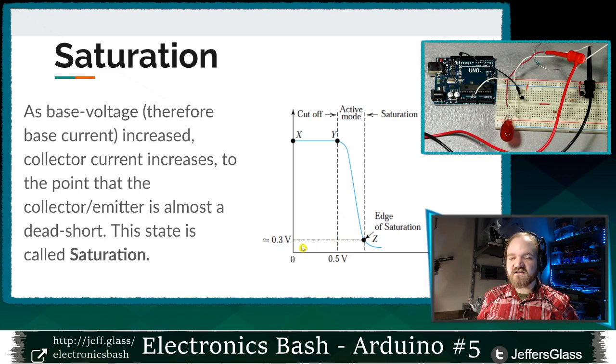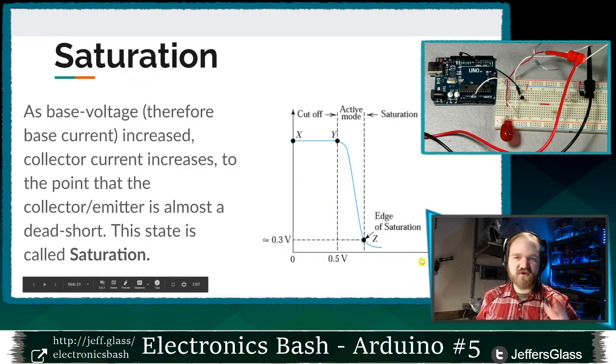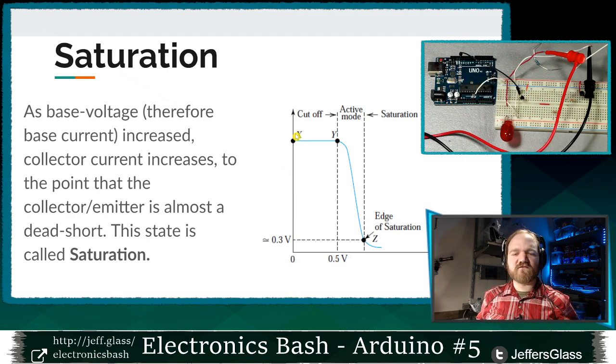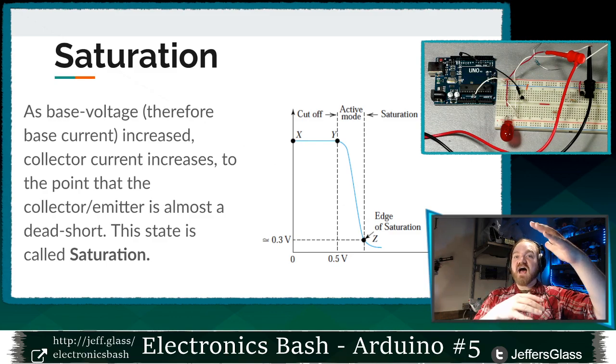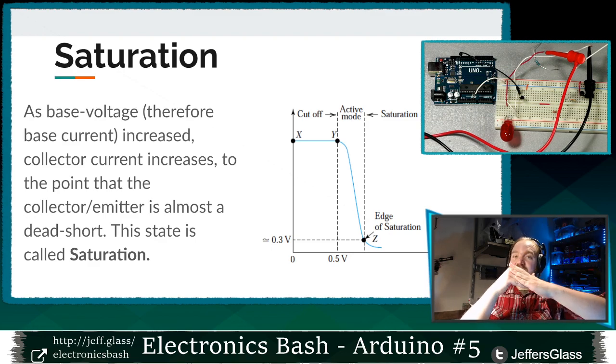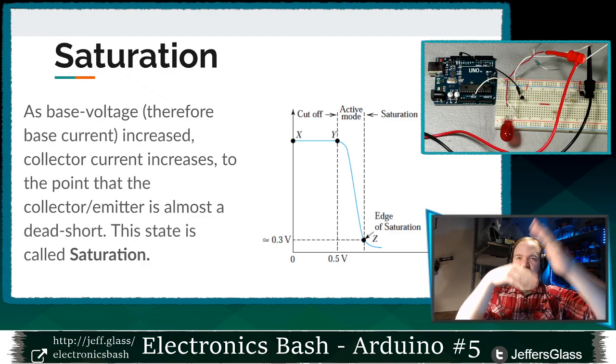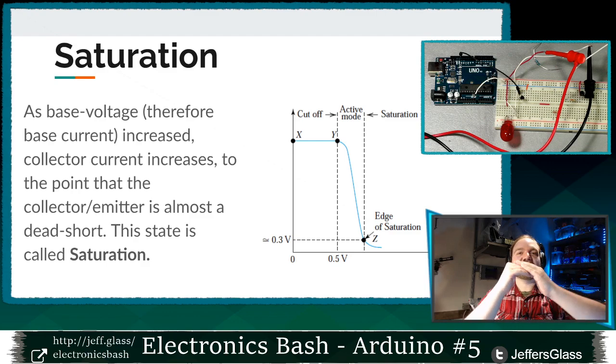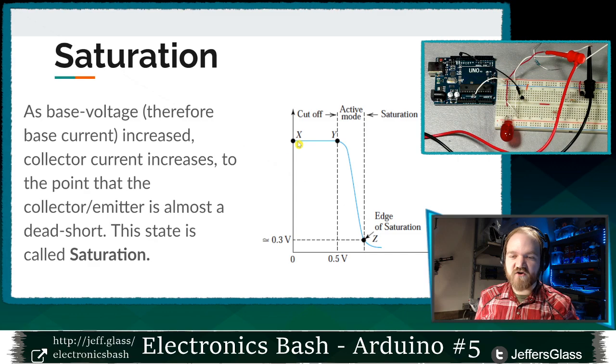So what we've got here is a little graph of the voltage across the bottom between the base and the emitter, right? We're applying a slightly higher and higher voltage. And here we have essentially the voltage across that base, the voltage across the collector and the emitter, right? If that voltage is high, that transistor is resisting things flowing. It's holding itself at a high intermediate voltage. And when it turns on, like closing a metallic switch, it's going to let the voltage across itself, the resistance across itself, become very, very low, right? So this is essentially a graph showing that, right?